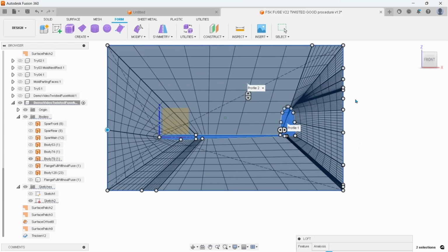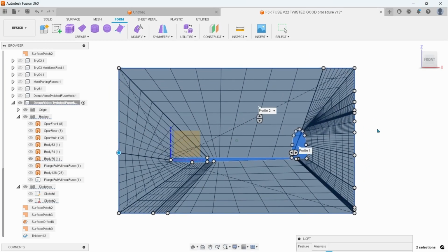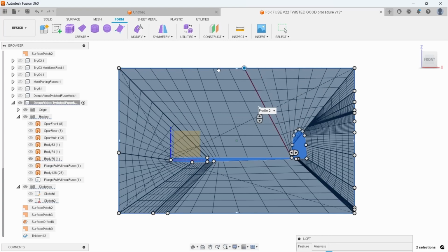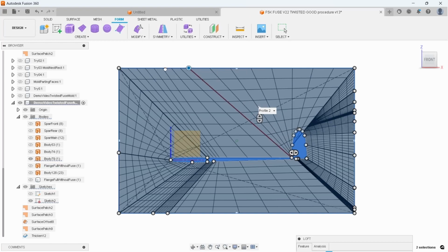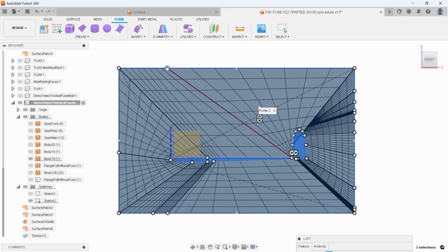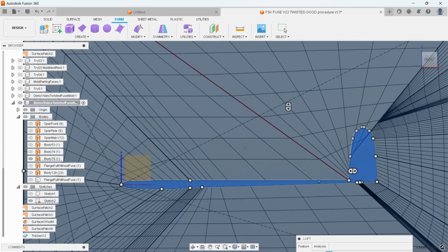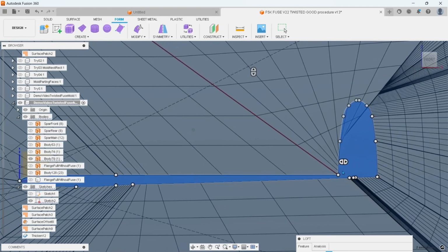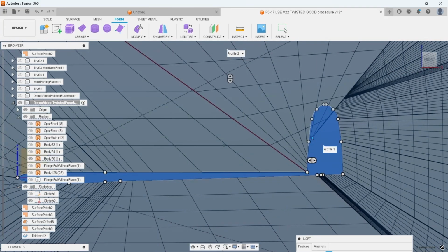I'm very happy with the result right now, but the work is not finished, because you remember that now we have to move these projected points, because they are not located at the exact and right position that we are waiting for. You remember here we are waiting around a 45-degree angle between the end of the fuselage and the beginning of the rudder, the linkage, because we start to have some offset.